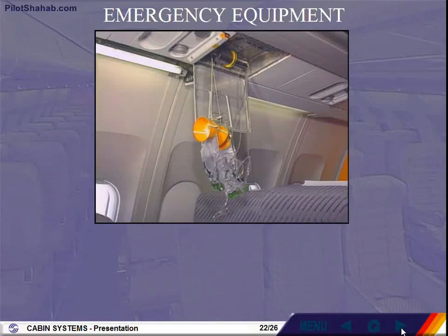The masks are provided with a flexible supply hose, a flow indicator, and a reservoir bag. They are attached to the generator by means of a pin, which automatically starts the generation of oxygen when it is pulled away from the cylinder. A door stop is used for the test procedure and prevents the masks from dropping. The number of masks contained in the unit is indicated on it.